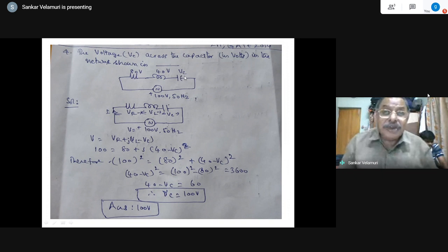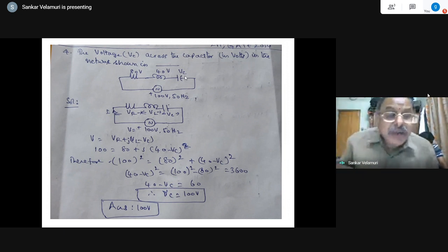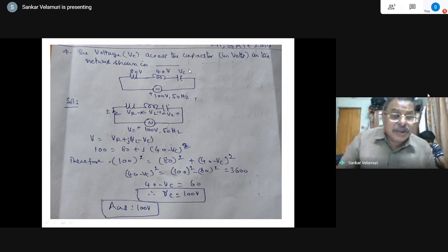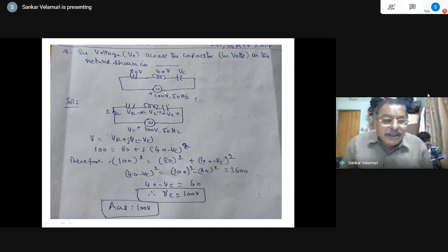Ohmic value of capacitance is more dominant than the resistance value of the capacitance. That is why its value is negligibly small. But it is an ideal capacitor here. But in case you want to include the internal resistance of the capacitor, it can be taken as infinity. Whereas the internal resistance of the inductance, if it is not negligibly small, you have to show that as the resistance, so that instead of a simple inductive branch here, you have to show that as an RL series combination. But anyway, since nothing is being mentioned, there is nothing wrong in choosing them as ideal elements. That is important, right?